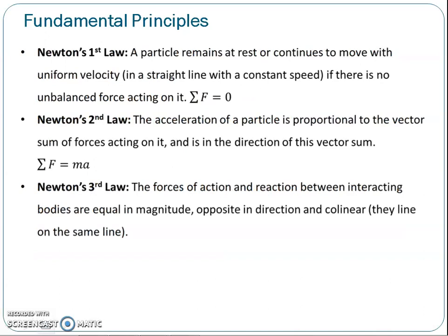We will be dealing with several principles in dynamics. First, Newton's first law, summation of F equals 0. Here, particles remain at rest or continue to move with constant velocity when there is no unbalanced force acting on it. Next, in Newton's second law, where we have summation of F equals ma, we are dealing with accelerating bodies. The acceleration of a particle is proportional to the vector sum of the forces acting on it, and is in the direction of this vector sum.